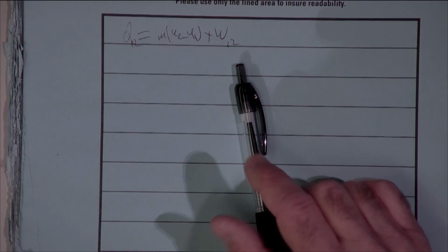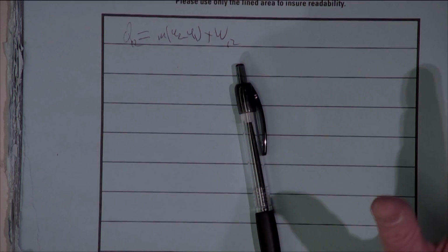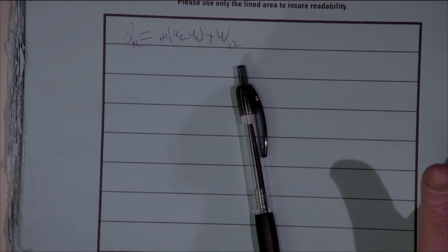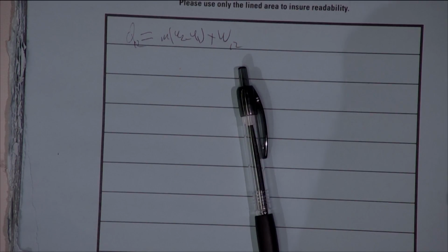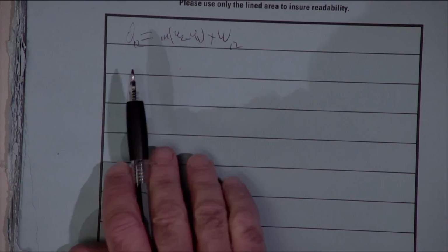For instance, one of the homework problems, which was maybe number 40 or something like that, had different types of work. Just got to make sure you include them all. What I would caution you on, though, is, I've mentioned how some of your terms are going to be positive, some will be negative, right? Heat added is positive, work out or work done by the system is positive, heat out is negative, work in is negative. Don't change the equation.